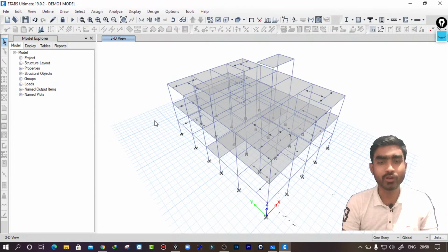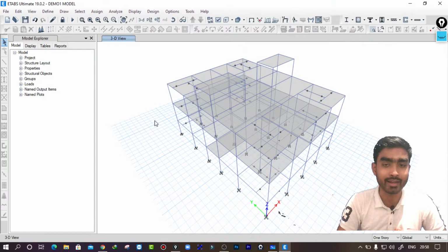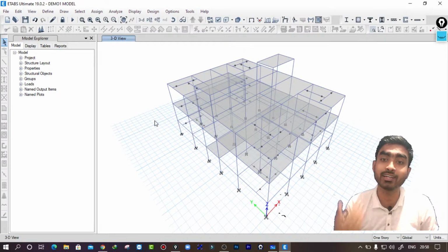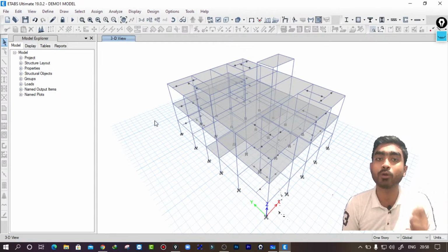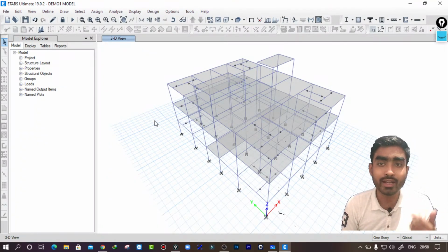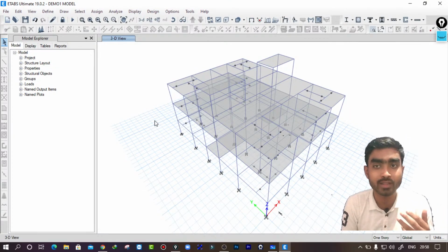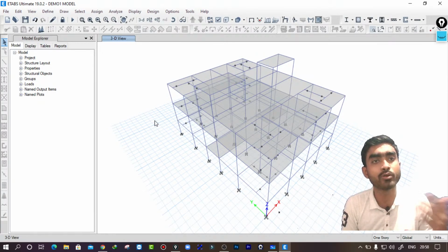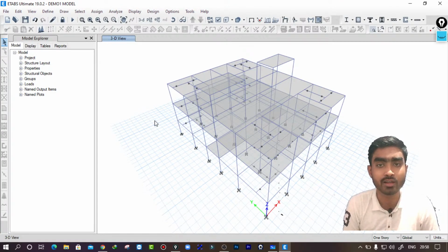But you should have a basic idea of how tall our structure is and how it should behave. As I have explained, you can calculate the degrees of freedom of the total structure and the levels like this also. Now if the number is exceeding, and you are not getting mass participation even after increasing the load cases, that means there is a problem in the model. To solve this, you can check the model again. If you cannot find any problem, there might be a small part of a beam which is extended, or a small node which you have left. Then you can go with Ritz vector analysis, and it will solve the issue.